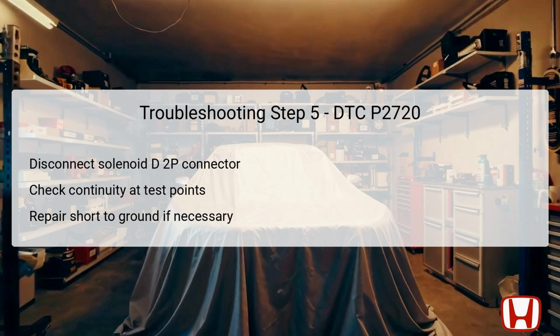If continuity is present, the system is functioning correctly, but if not, it indicates a potential short to ground in the LSD wire that connects the solenoid to the PCM. Repairing the wire is essential to restore proper signaling and functionality.